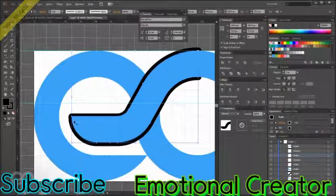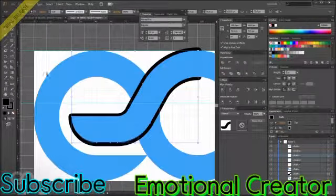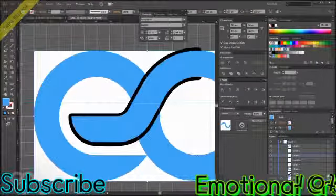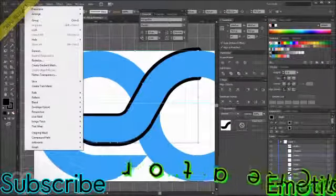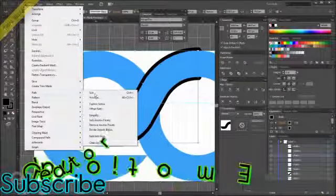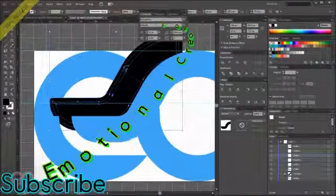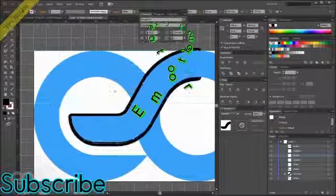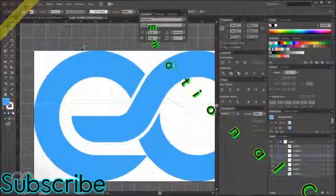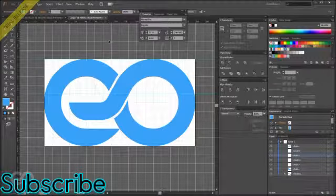So basically what I want now is the object which I have selected. I want this to basically go ahead and trim out this value, but I want the outline to be used. So for that, I can select any object. I can go to the object panel, and over here I can tell path, outline, stroke. So when I do this, it basically creates an object which is an outline itself. So it creates paths for the outline. And now I can go ahead, choose these objects and trim. So now a perfectly good logo which I can go ahead and use anywhere I want.